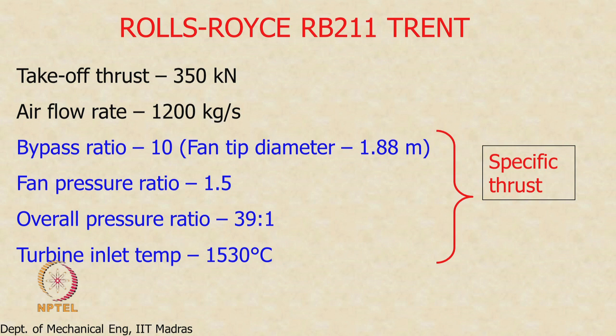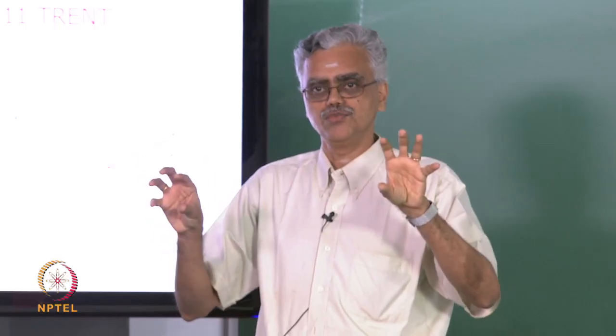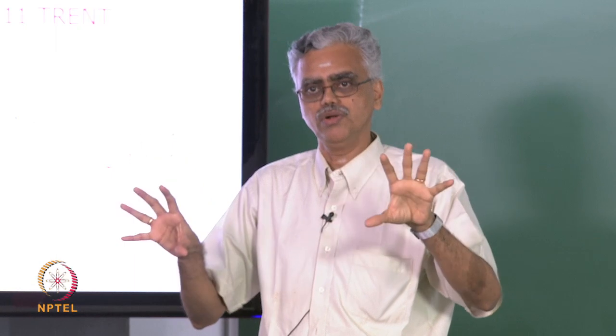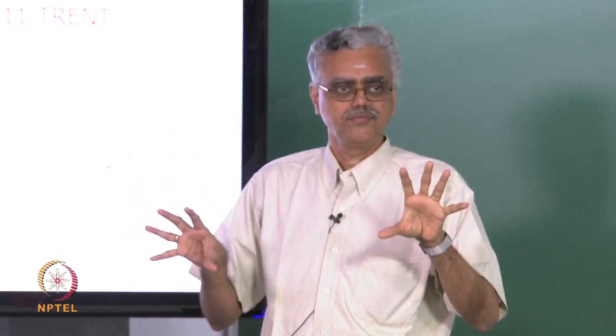So now if you start thinking about m dot delta V for this air, you see that m dot is very large, right, and this pressure rise will only give rise to a small velocity change. So you can see that m dot is very large, delta V is very small for the fan. It is very similar to the propeller from that perspective.